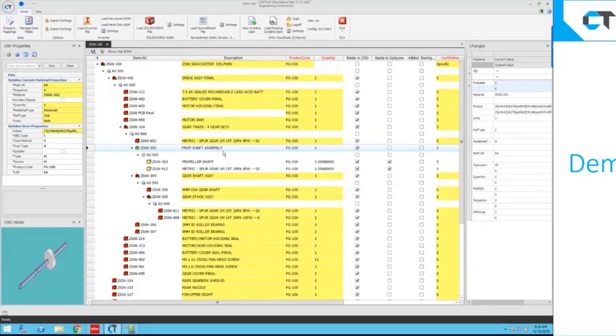If you want CSI to retain the changes that you made before, in this case the description, like I did here, it retains the description if it's not a new item. These rules can be changed at a field level. You could say, in the case of description, always come from SolidWorks. But in the case of product code, obviously, always come from CSI. We have super flexible rules for how this data gets brought over and how it's merged.